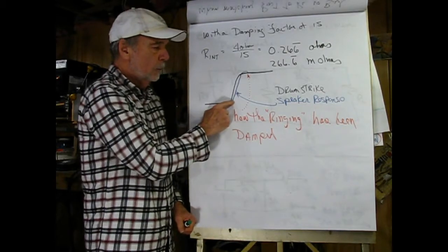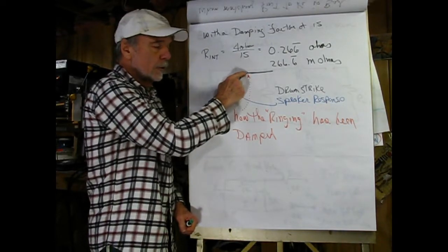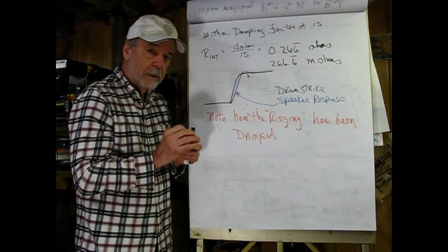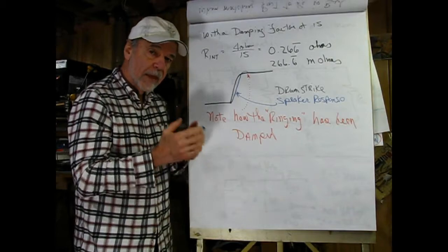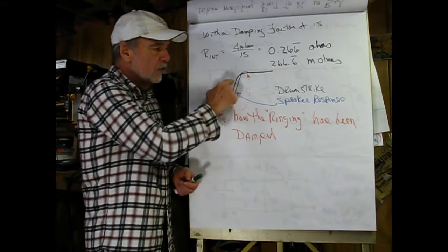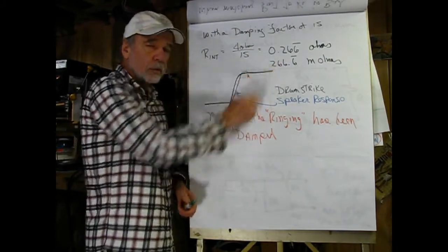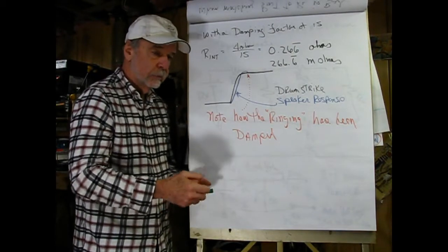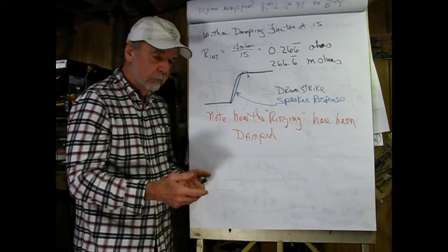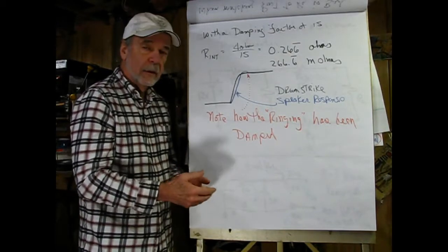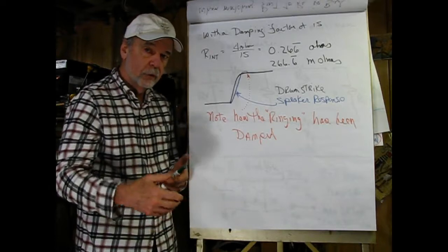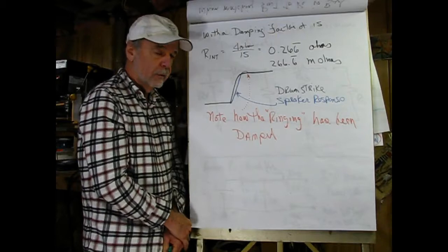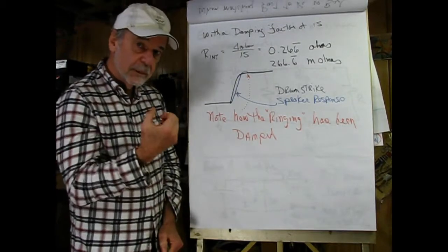So what happens now is that here's our electrical signal again in black. Here's the speaker cone in blue, accelerates, gets to the top. Now, as the cone continues to move, the voice coil in the speaker is cutting a magnetic field. And that is a power source. And that is basically feeding a very low resistance of the amplifier. And like a car, sometimes when you turn on the headlights, you might hear the alternator belt squeak. That is because more mechanical energy is being converted into electrical energy. So the amplifier effectively shorts out the speaker, which is acting as a power source.